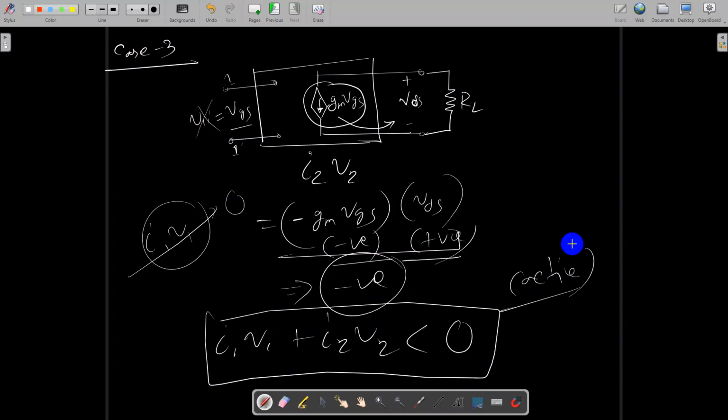So basically the MOSFET was not an active device. We are forcefully making it an active device. It's our work. It's the analog designer's work to fight those non-linearities and make that thing active. Okay, so the MOSFET is an incrementally active device for the small signal model.